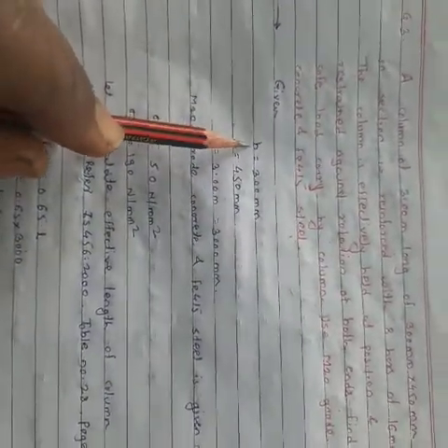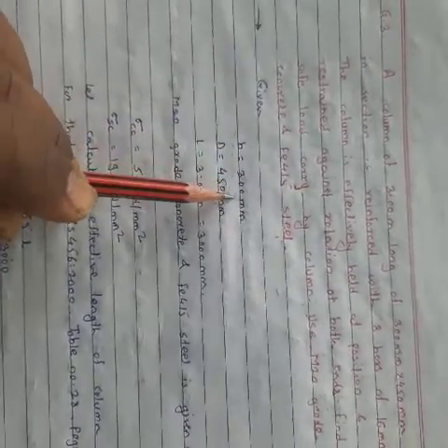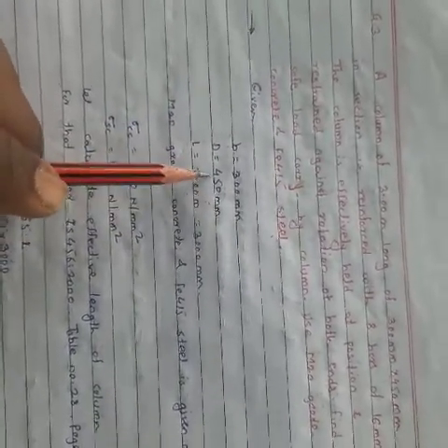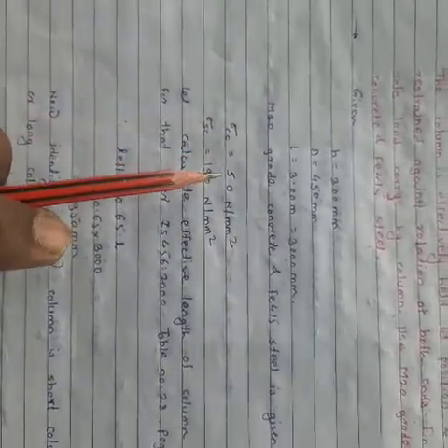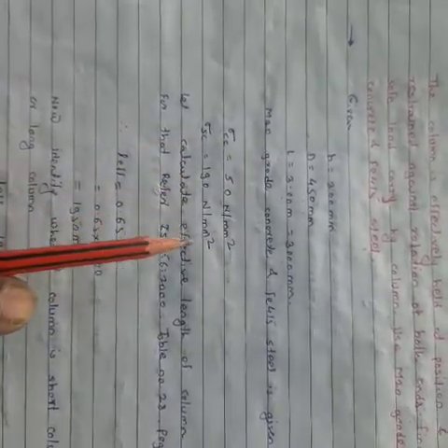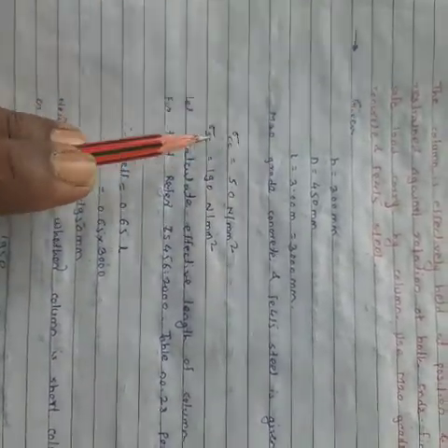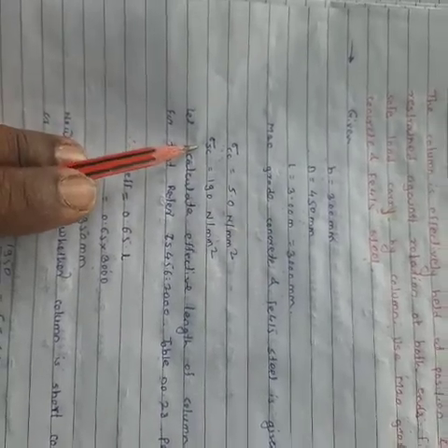So first you have to write down the given data. What is the given data? Dimensions of the column are given. B, that is the width of the column, is 300 mm. D is the depth of the column, that is 450 mm. L is the length of the column, which is equal to 3000 mm. Again the M20 grade concrete and Fe415 steel are given. So you have to calculate the material constants, that is sigma cc, which is equal to 5 Newton per mm square, and sigma sc is 190 Newton per mm square. We are getting these values from IS 456 2000, page number 81 for sigma cc and page number 82 for sigma sc. From that we are getting the value of the permissible stress in the material.